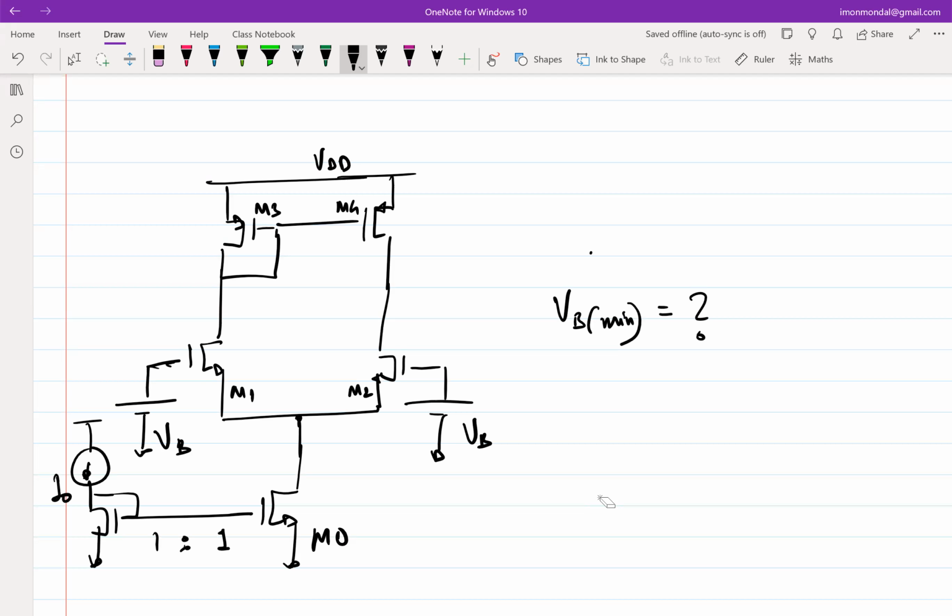The drain of M1 is a fixed value. Okay. Why do you think the drain of M1 is a fixed value? Because current will be divided equally in both the branches. Right. So M3 has source fixed. So let's put the current together. This is I naught. So if everything is symmetric, this current will be I naught over 2. This current will be I naught over 2.